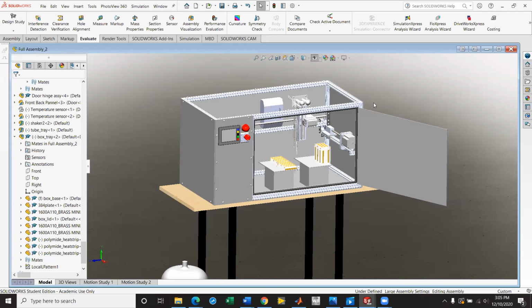Okay. And then my other quick question is, are you guys confident that the 80/20 is going to be, I guess, straight enough? And the mechanism that you guys are essentially using is a clamping system, right, to constrain the motion linearly. Do you have a way to adjust the force of compression on the 80/20? Or do you just bolt it on and it is what it is because the holes are drilled in one location? Yeah, I think the latter.